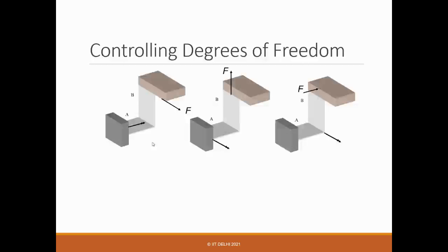So although it looks like a very simple component, if it's used and designed properly, you can design a very nice mechanism out of it. So this is one example. If it's folded along the fold line, you get a very high stiffness, and it gets constrained along that line. So what do you see if you are applying force here?